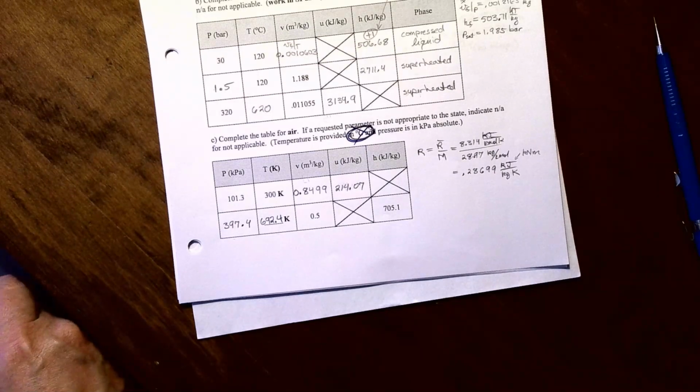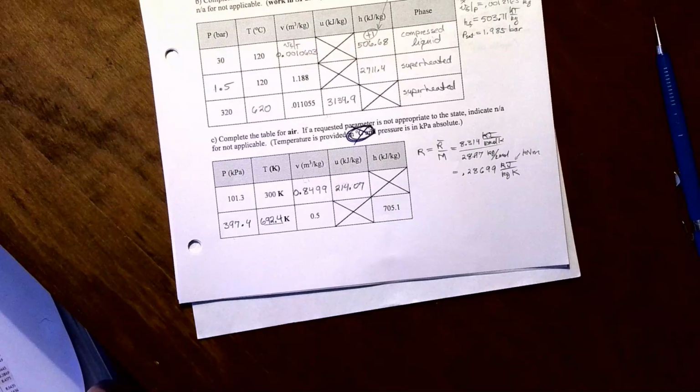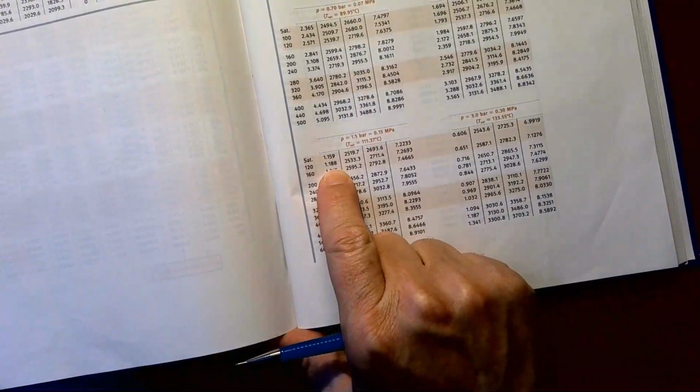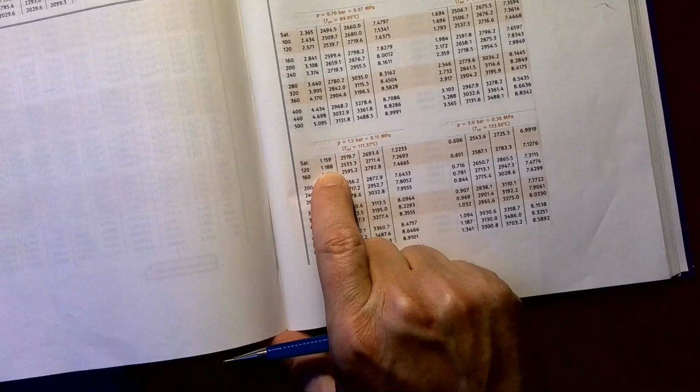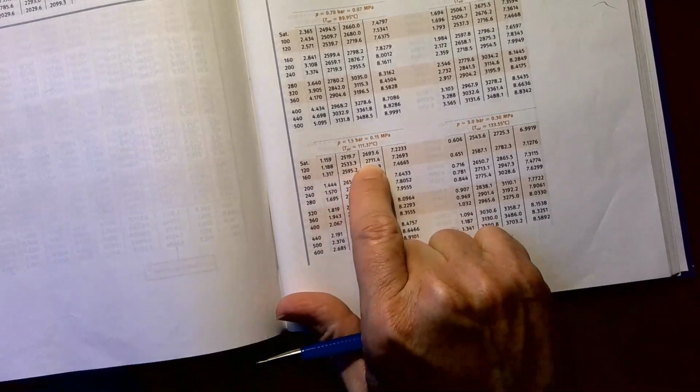That was a little bit challenging to find, so I'm just going to peruse through the pages here that you can't see yet. I'll show you when I find it, and check what is V at 120. Just perusing the tables, I actually found 1.188 exactly in this case for a pressure of 1.5 bar. So no interpolation needed for this one. To get U and H, the values are here directly, and the pressure is 1.5 bar.